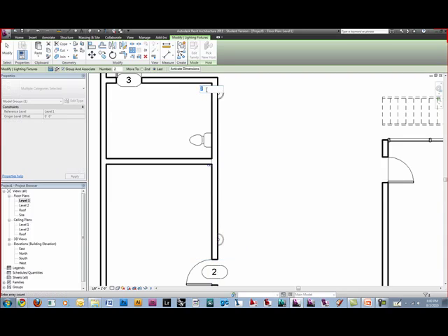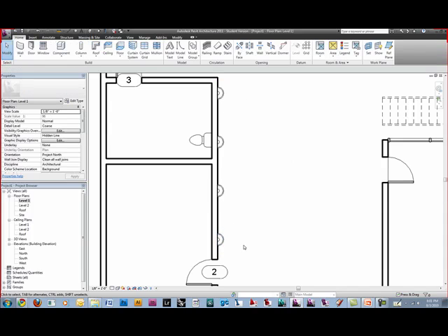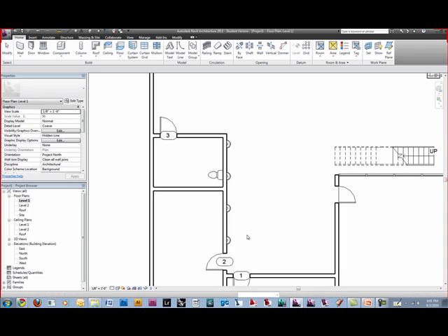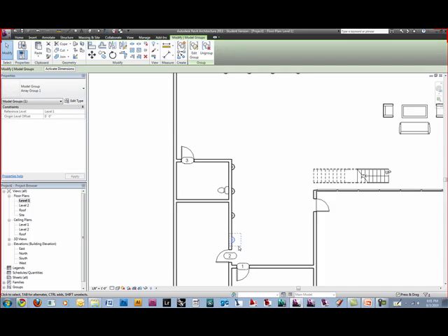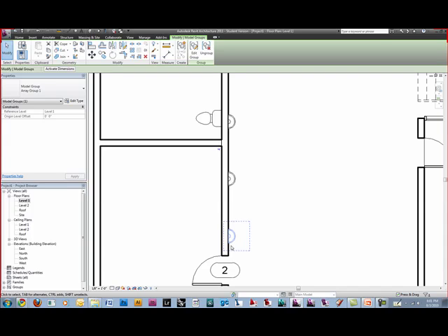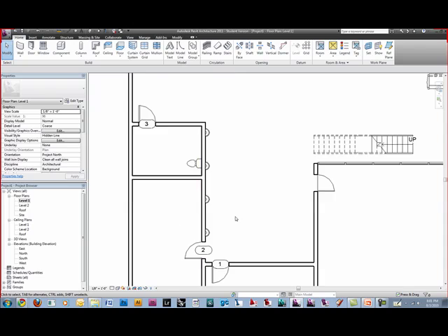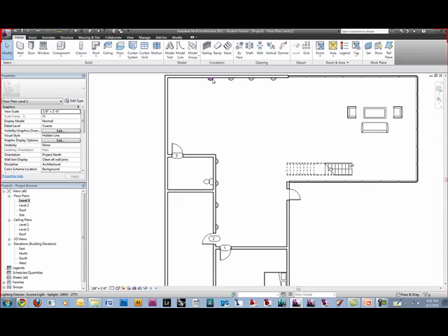And then you see this little number pop up. It's saying how many of those do you want to be arrayed. So let's say I wanted 4 fixtures, and then you hit return or click off, and now I have 4 evenly spaced fixtures. It's actually really cool if you're doing really large spaces. You could always move that last one as well, and it'll just adjust the space. Yeah, so if I move this, I'm just hitting nudge right now. But if you look closely, every time I nudge, it will still space them out evenly. It's moving the lights. So it's really cool. Array can be a pain in the butt sometimes, but on the whole, it's generally a good command.